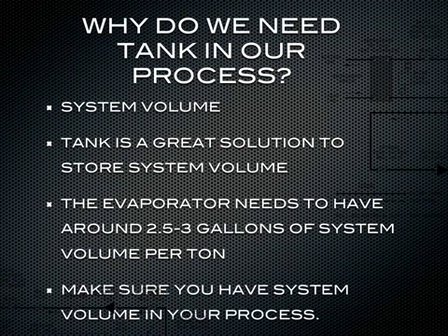If you don't have enough system volume in your process, you're basically going to short cycle your compressor and shut down your refrigeration system, and the piece of equipment is not going to get cooled.